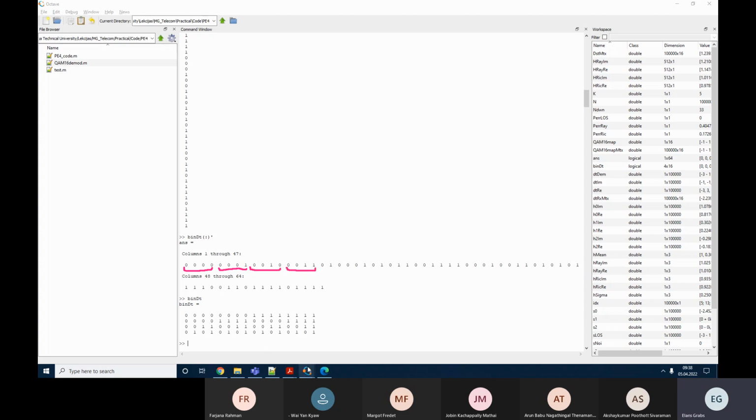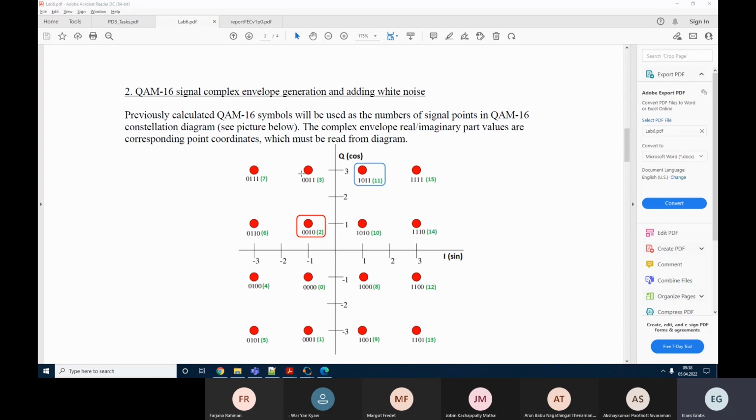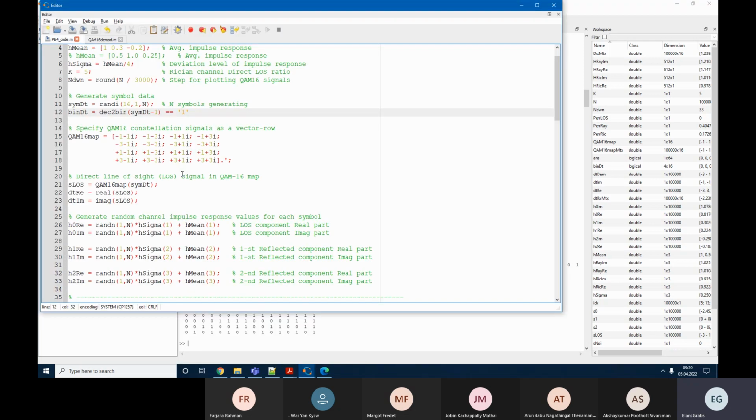And these symbols actually match this constellation and use the same numbers. So basically, we now have gray mapping. Yes, here we used gray mapping for this. No, in fact, it's not gray mapping. Yes, you can see here that this. No, wait a minute. Everything is fine. It is gray mapping. We have only one different symbol. As I said, later in our course we are going to talk about trellis coded modulation, which is even stronger than gray mapping as a way of assigning symbols, because it also uses some coding in the process, error correction coding, right?